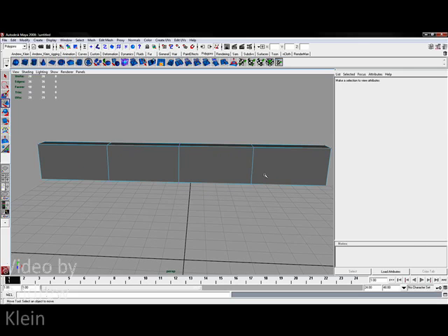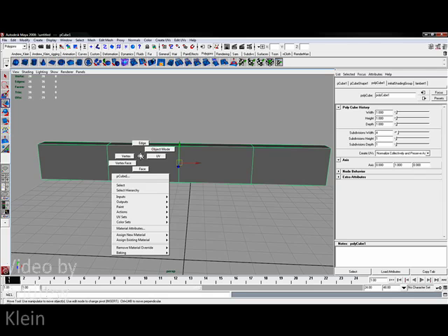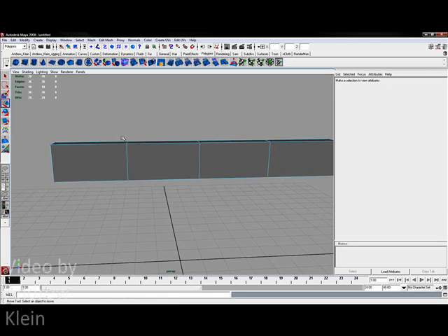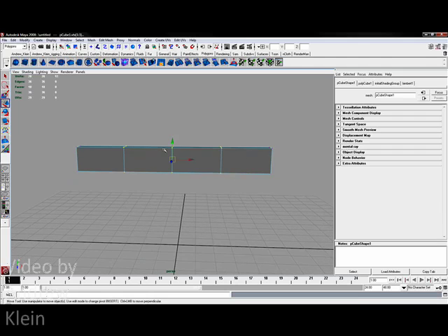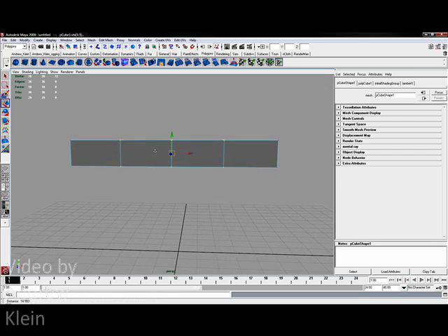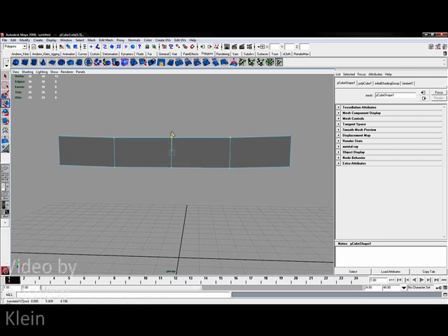My mesh, as you can see now quite clearly, is a teal blue color instead of being a green wireframe like it was before. The vertices are the intersections of your individual edges, and it's these which I can drag a selection over to alter. To create curvature, I'm just going to nudge these down a little bit with the Move tool.